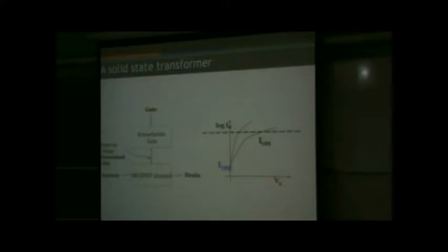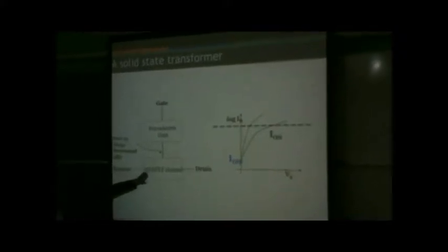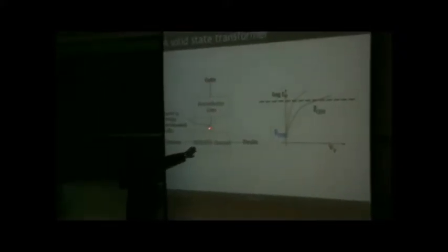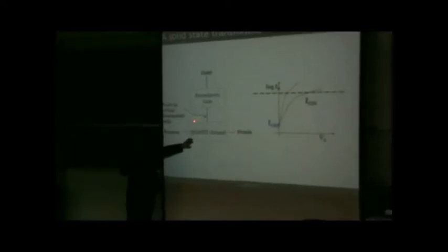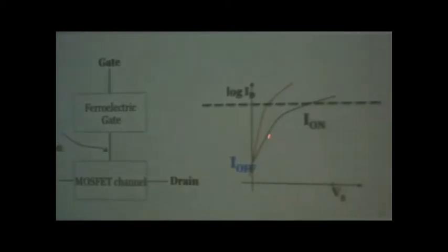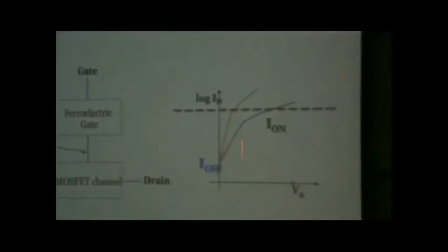And if this is a MOSFET channel, and if I can boost the supply voltage at this channel node, then my IDVG, rather than looking like this black curve, could look like the red curve, because I'm actually increasing the electrostatic voltage right on the channel. And that can help us reduce what we call the subthreshold swing, but just from this curve, that can help us get to the current level that we want at a smaller voltage. So that can help us reduce energy dissipation.